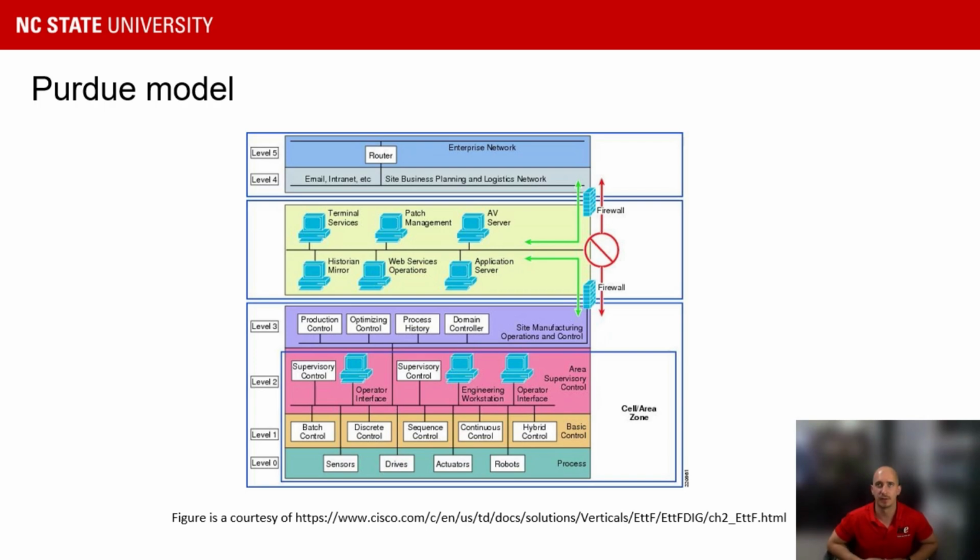This model does not fit the IIoT paradigm since device assets on the shop floor will need to access cloud-level resources. MQTT Sparkplug B can be applied to the existing Purdue model and allow access to the data from the IT level and send additional data from machine learning predictive systems to the OT level.